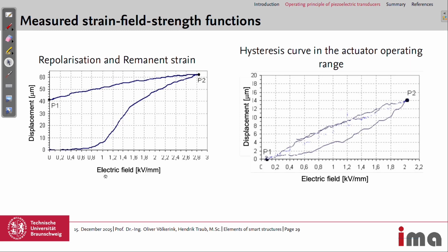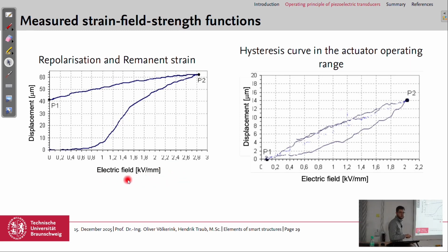So you multiply it with the thickness of your material, and then you get the voltage you need. If you have 0.5 millimeter thick material, you would need 1.4 kilovolts. And if you have material which is 2 millimeters in thickness, you would need 5.6 kilovolts. Yeah. Distance between the electrodes.